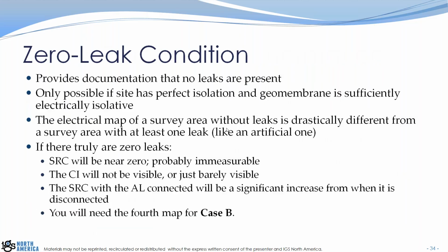So let's talk about the zero leak condition. This is the documentation that can show that there are no leaks present in the survey area. How do you know for 100%? Well, the survey area has to be wet. If you don't allow the facility to leak, you can't say for sure whether there's a leak there or not. I know through painful experiences that if a site is too dry, you won't detect leaks, even largish leaks like a 1-inch puncture.